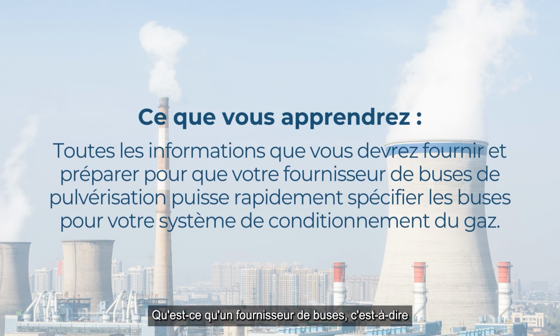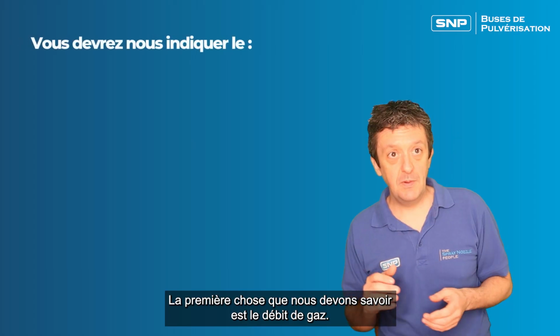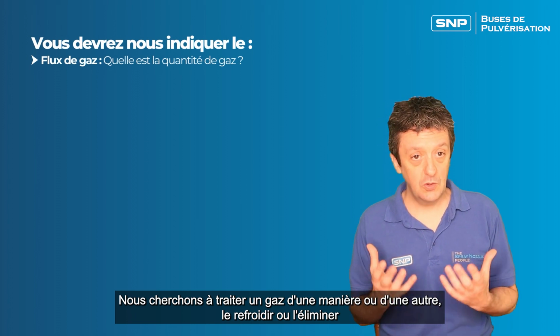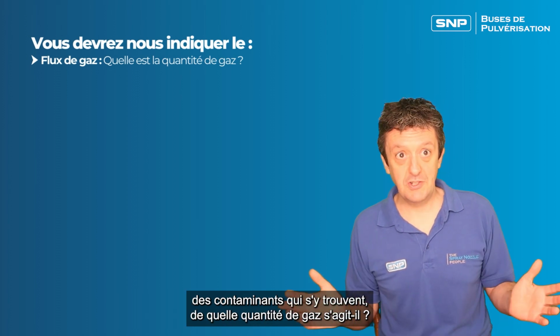What does a nozzle supplier, i.e. us, need to know before helping you specify nozzles for your gas conditioning system? So the first thing we need to know is the gas flow. We're looking to treat a gas in some way, either cool it down or knock out some contaminants in there. So how much gas are we talking about?